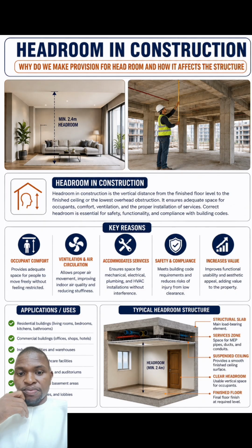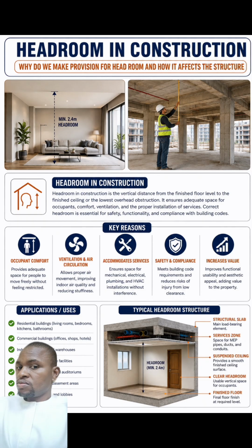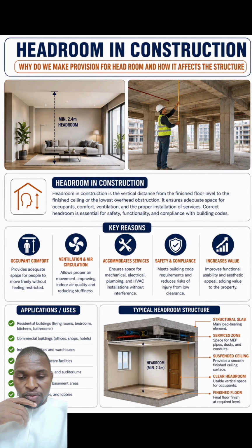So, occupant comfort. The comfort of the occupant is very essential, because you can't build a building whereby it becomes uninhabitable. Sometimes you see some people construct a staircase and the first flight is too high, so the second flight will be too small, and it becomes very difficult for you to scale through into the first floor of the building, which leads to discomfort of the occupants, right?